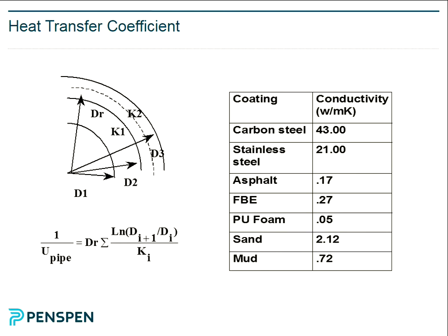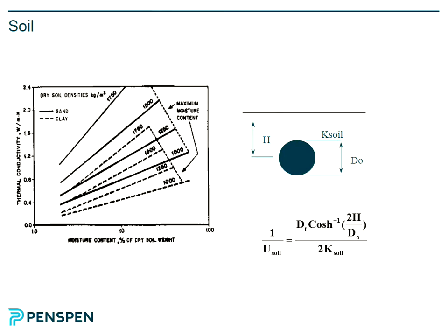So if you need to maintain your product temperature to a very high degree, in other words, you can't go below something which is quite high, then you're talking about big money. Typically, bare pipe is about 300. So you can see the difference in heat loss for the same diameter pipe. This is losing heat 300 times quicker than the other one. So 300 meters of this pipe is equivalent to 1 meter of the other in terms of heat loss.